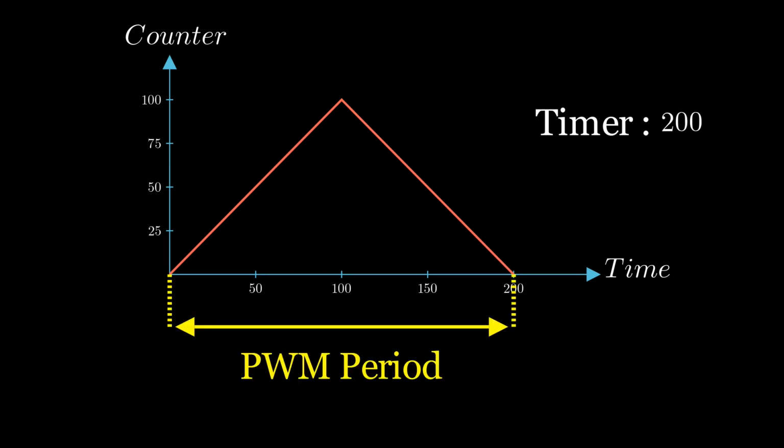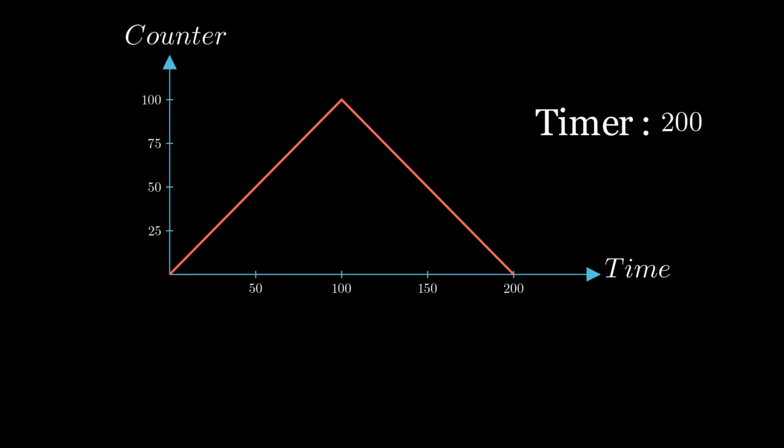So we start by first figuring out where we are in the current PWM period. Let's say we're somewhere here. Next up, based on the desired voltage, we set the desired duty cycle, which translates to the compare value. So the maximum counter value will correspond to a duty cycle of 100%, and a 0 will correspond to a duty cycle of 0%, or vice versa, depending on the configurations. Let's say our desired compare value is here.